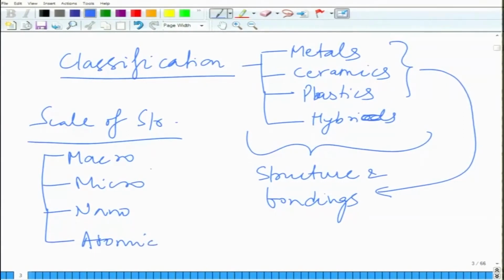Now, in the context of materials engineering, we are interested in microstructure, which is the structure and distribution of phases, grains, grain boundary, etc., impurities, inclusions at micron level or submicron level scale. Nanostructure could be again related to same as microstructure, the formation of nanocrystalline phases, nanocrystalline structures. So, micro and nano are something which can be viewed by microscopy, and they have very profound impact on the properties of materials. Fourth is atomic structure.